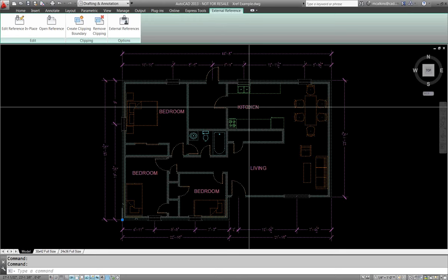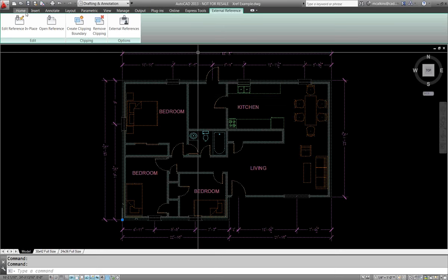If you're talking about managing the layers within the XREF through a viewport, those are overridden or managed just the same way that you would any other layer. You go through the viewport and turn on and off or freeze and thaw layers that are XREF dependent. So it is possible to place an XREF on whatever layer you want.